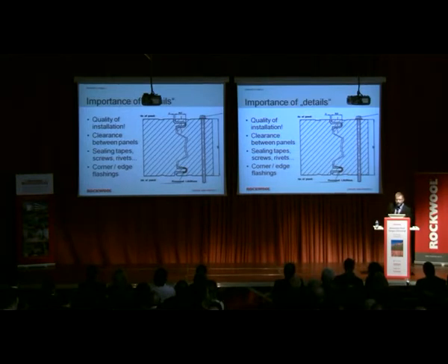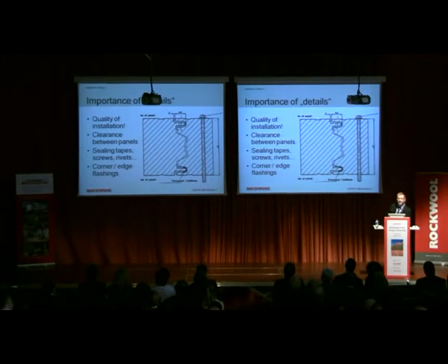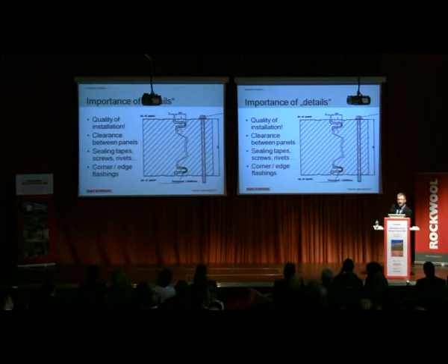Of course, if you have a nice fire test result, you can achieve it with a construction built in a test furnace, but what happens in real life, in real buildings, may be quite different. I cannot stress enough that quality of installation is paramount. This is the basis of the construction, that it performs in the same way as it performed in the fire test.